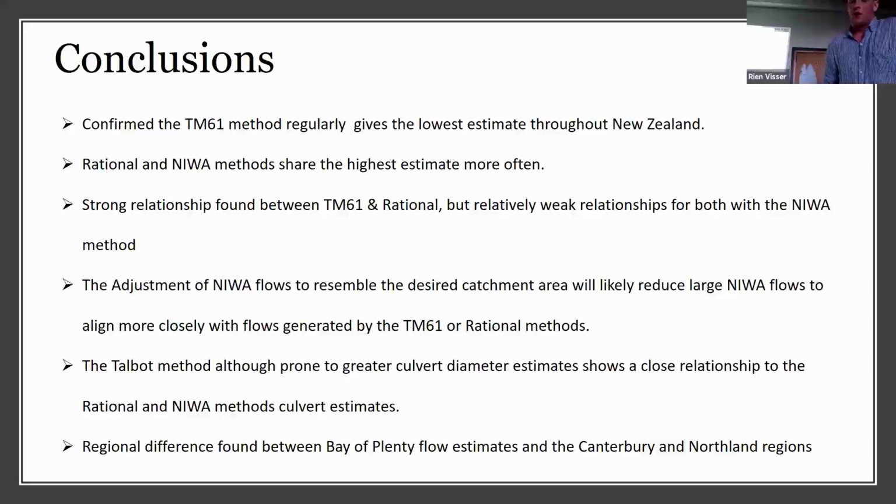The Talbot method, although prone to greater culvert diameter estimates, shows a closer relationship than expected to the rational and NIWA method culvert estimates, and there was a regional difference, with the Bay of Plenty showing different standout characteristics than both the Canterbury and Northland regions.